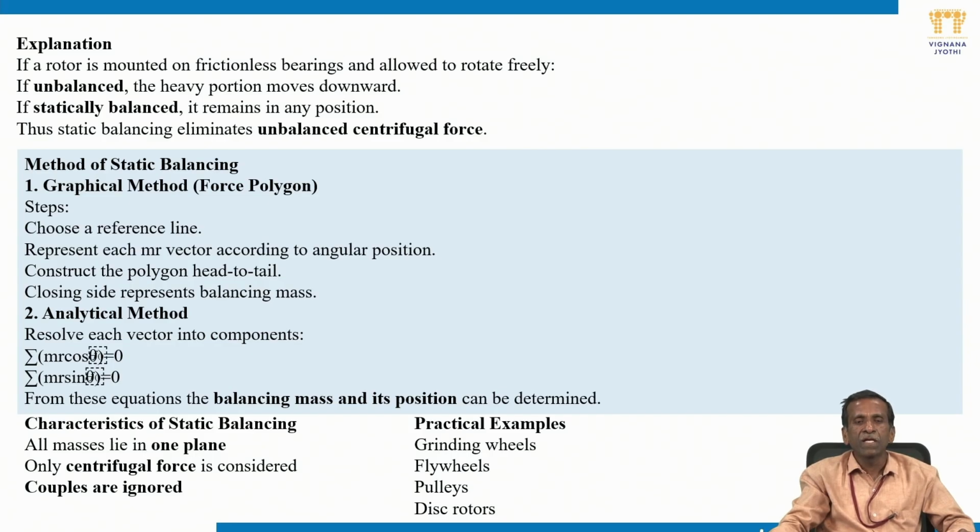In the empirical method, because different forces have different orientations with the reference axis, whichever we choose, we resolve these forces into components with respect to the reference axis and perpendicular to it. The algebraic sum of these components in any direction must be 0. Then it is balanced. Otherwise, the unbalanced result, whatever it may be, needs to be balanced by incorporating a mass with a chosen radius. How we can calculate this, we are going to see soon.